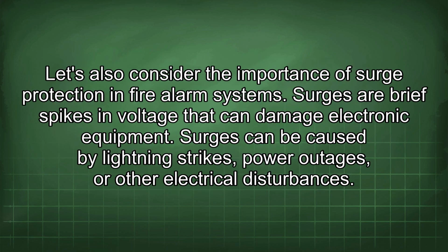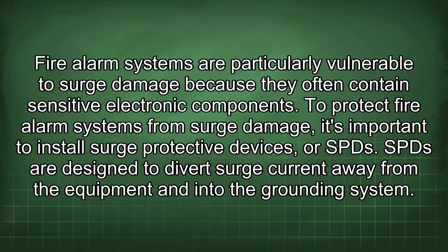Let's also consider the importance of surge protection in fire alarm systems. Surges are brief spikes in voltage that can damage electronic equipment. Surges can be caused by lightning strikes, power outages, or other electrical disturbances. Fire alarm systems are particularly vulnerable to surge damage because they often contain sensitive electronic components. To protect fire alarm systems from surge damage, it's important to install surge protective devices, or SPDs. SPDs are designed to divert surge current away from the equipment and into the grounding system.